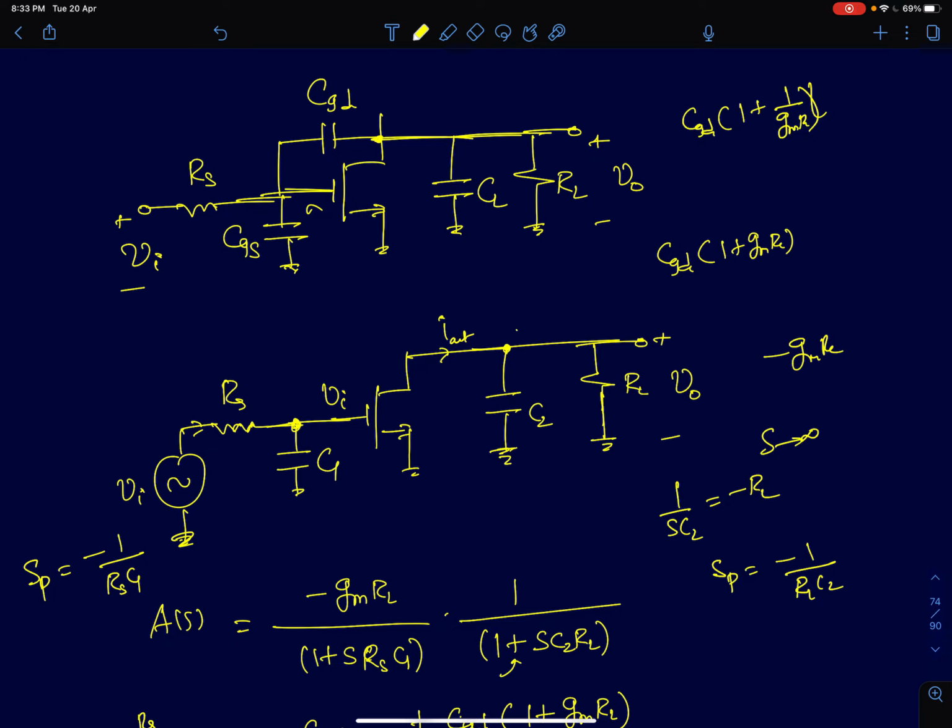the frequency response of MOS amplifiers. We also spoke about the various parasitic capacitors in a MOS device, and their impact on the frequency response of the MOS amplifiers. We started with our analysis on a simple common source amplifier, and we said when you include the gate to drain capacitance between the input and the output terminals, the mathematical analysis becomes much more complicated. And we said we are going to make some simple approximations using Miller's theorem and derive the poles and zeros for the system.